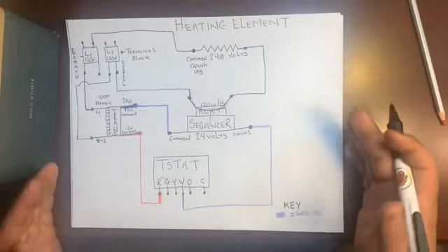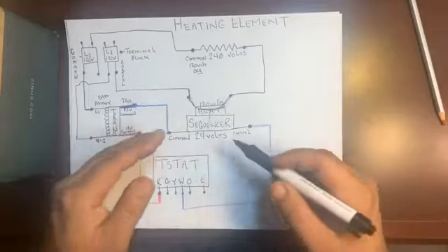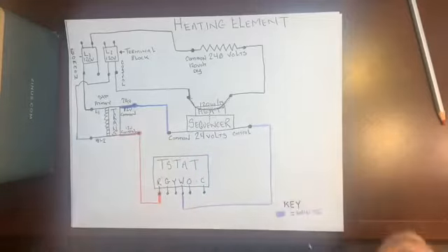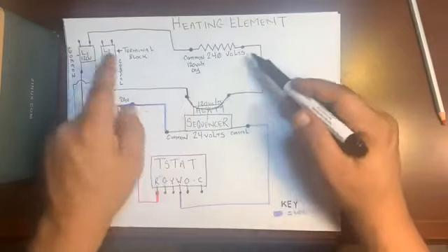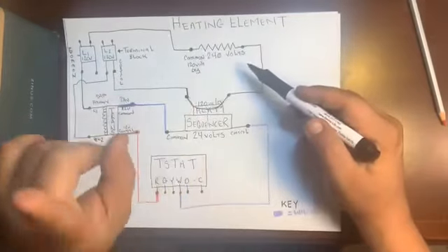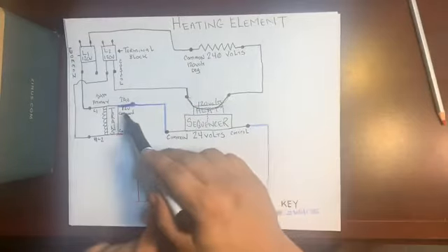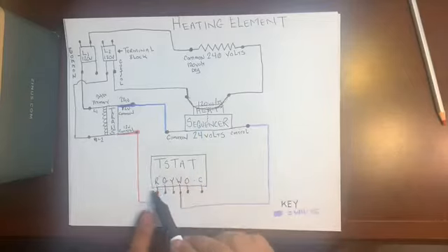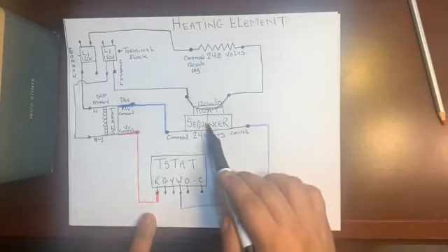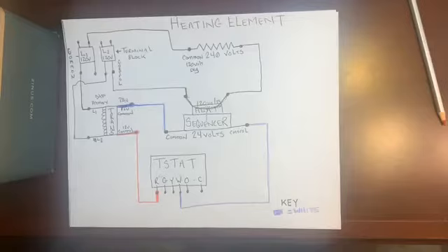When we tie it into this, what do we see? What is a relay? I say again, a relay is a relay is a relay. A relay controls this high voltage, and what does it control it with? Low voltage, 24 volts. And remember, 12 of the volts are already at every relay. We're only shuffling 12 volts through the thermostat to turn on when we want to close this relay, bring it up, close the circuit, and turn on the heating element.